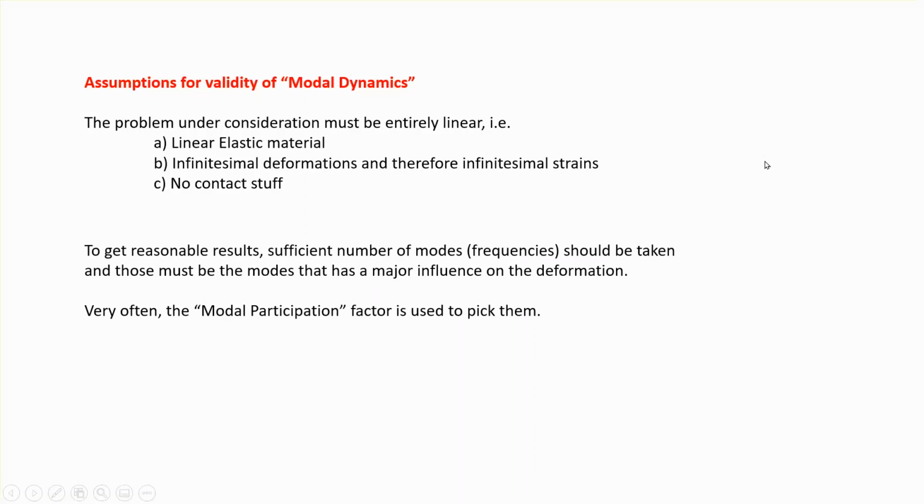Now, there is something else that one should be aware of, and that is sufficient number of modes must be taken in a realistic problem. Not only sufficient number of them, but also modes that actually have an influence on the nature of the loading and deformation. And very often, this is done internally by the computer using the modal participation factor that is generated. But our problem is simple, so we're not going to worry about it.